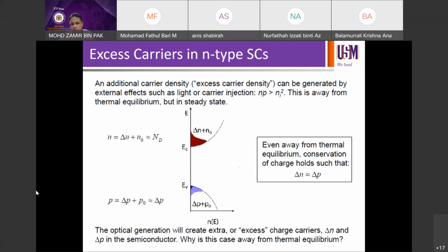So we stopped on this page yesterday where we discussed the change in the carrier concentration when you have excess carriers. On this page, you can see that excess carriers, as an example, is explained in terms of N-type semiconductor, where we expect more electrons to be generated into the silicon, and therefore that will skew the distribution so that NP is more than ni squared, right?